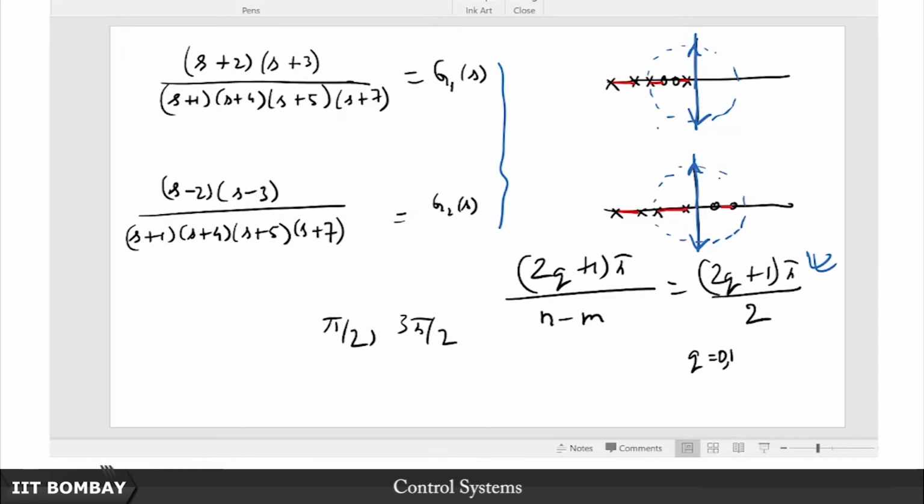It makes no sense to say that both these root loci should be along the same direction, at the same place, because we know that you cannot satisfy the angle criteria at the same point for both of these kinds of root distribution. So effectively that asymptote is not telling me anything when the value of k is not as large as I want it to be.